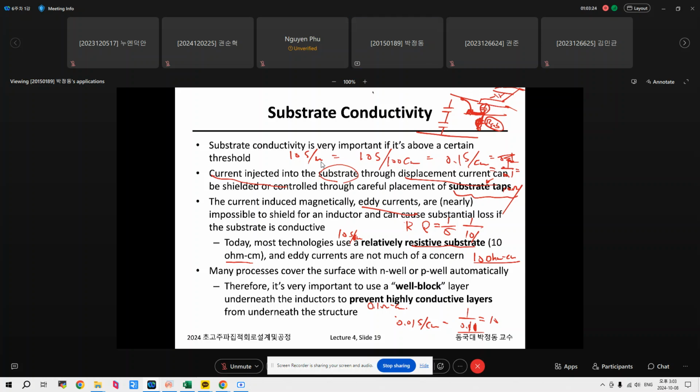So the easy peasy way to find the well block for different types of process is just to investigate automatically generated inductors. You just pattern the inductor layers and take a look at each layer. Then you can easily see what is defined as well block.